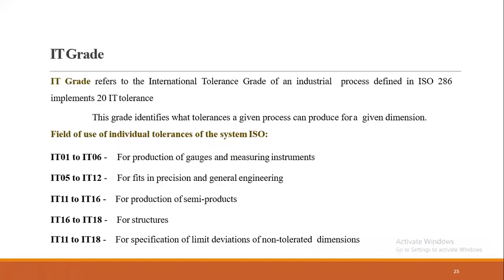Then these are some IT grades. IT grades means international tolerance grades. These tolerance grades are divided into these five types. From IT01 to IT06, this is used for tolerances for production of gauges and measuring instruments.